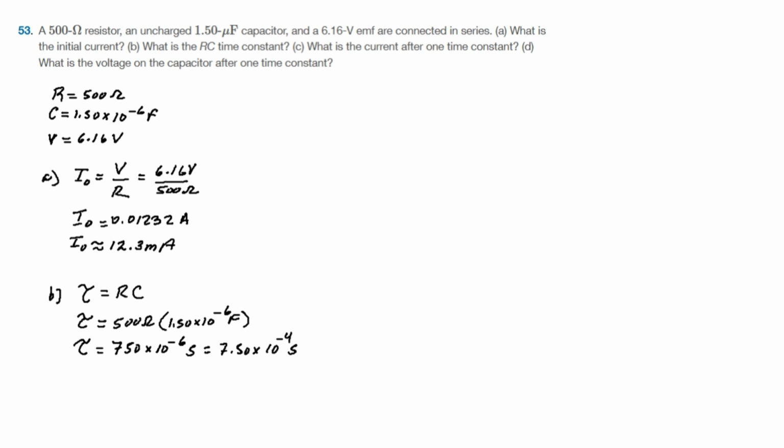So for such a time constant, we cannot appreciate the variation with the voltmeter. That's why I used in the experiment those high values of capacitance and resistance, because like that my time constant was 40-something seconds, and we had a chance to see the variation of the voltage in the voltmeter. But with this time constant, there is no way to see anything. It's very small.